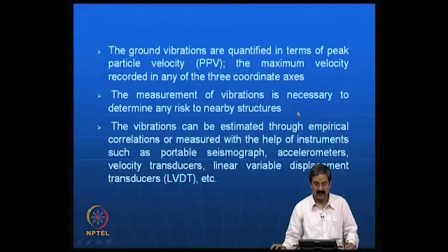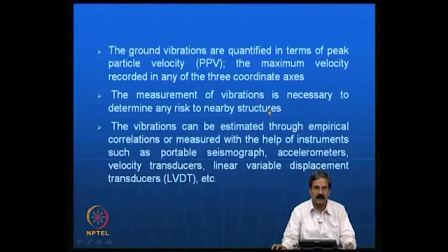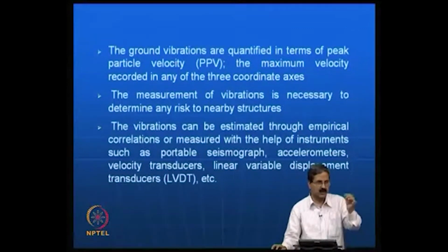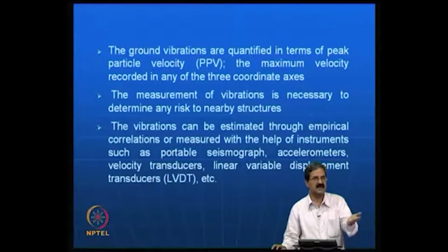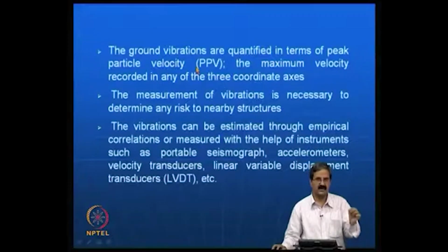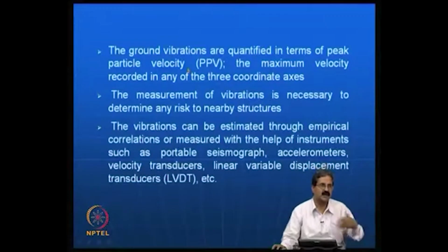So, this is one of the important ways in which one can measure the vibrations, and without vibration measurements it is very risky. We get a lot of cases where, because of the traffic, there are a lot of problems. So, you have to measure the vibrations before taking it up. Even if you are trying to construct a road or a big project, first take the velocity measurements, then construct it. If the peak particle velocity is within acceptable limits, then you can say that my structure did not cause any difficulty to you.